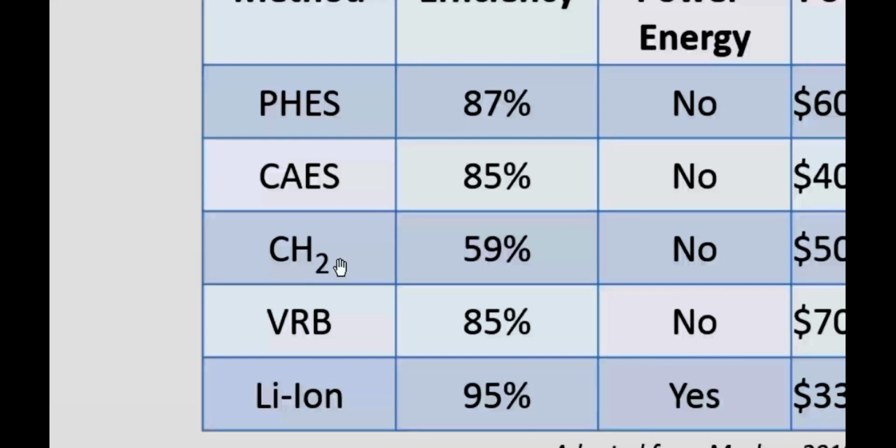At least in these two cases, your efficiency is largely governed by the efficiency of your turbines and pumps, which can be relatively high recently. Pump technology has gotten decently good, especially in reversible flow ones. Batteries have relatively high efficiency, at least in the round trip during their cycle lifetime. Obviously, batteries have a limited cycle lifetime, which is another aspect that I've considered in their use case, and which is also why they're so expensive. And then hydrogen in the middle there. Hydrogen is exotic and it's still a long ways off. Depending on which fuel cell you use, you get widely varying efficiency. Your electrolyzer also has a widely varying efficiency, so it largely makes sense why it's the lowest.